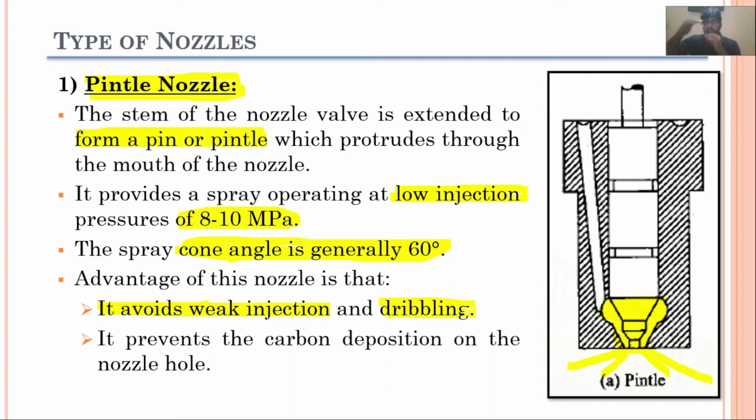So when this nozzle valve has closed, pintle nozzles usually do not allow the fuel to get into the combustion chamber, while this problem is very common in single hole nozzles. Similarly, it also prevents the carbon deposition on the nozzle hole as well.